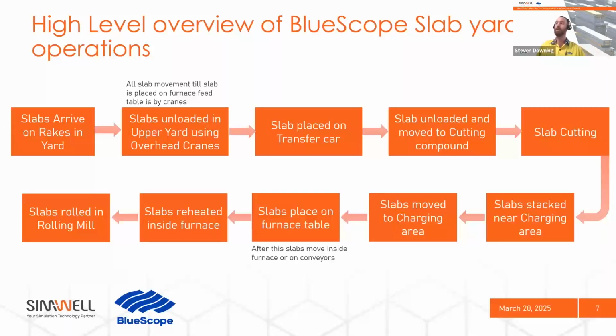So the slabs must be ordered, and when placed in order, put in front of our reheat furnace for the second crane in that area to charge them onto the feeding tables, where they are then put inside the furnace. We have to make sure as part of this process that they receive the correct heating dynamics, correct time inside the furnace, before they're then discharged and rolled.